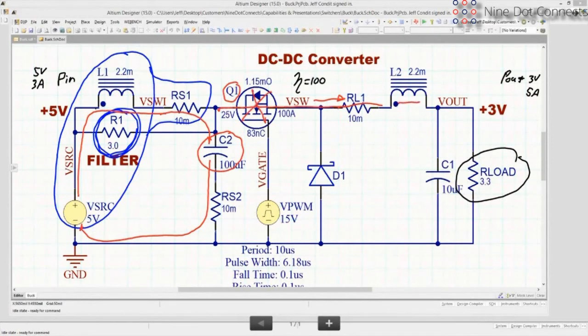When the switch switches off again, the inductor is going to keep that current flowing and has to pull it from somewhere. So it pulls it up through the diode. So the current in the output is going to continue. It's going to have a DC component going through the load, and most of the AC is going to be going through the capacitor, which acts as a filter for the current to keep the voltage on the load constant, to get rid of the ripple. And of course, as it flows out of there, it's going to be coming back to feed the inductor path.